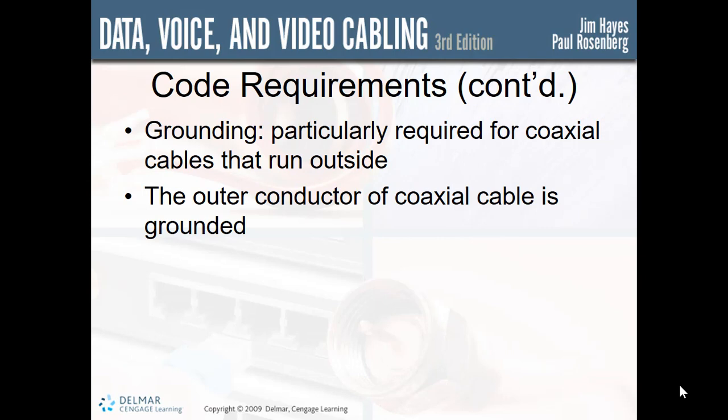Grounding is mentioned in both Parts B and C. Grounding is strictly required for coax cable runs outside of buildings. Although the NEC does not specifically state that all outdoor cables must be grounded, almost all outdoor runs must be grounded to meet requirements of the article. The concern with outdoor cable runs is that they will be exposed to lightning strikes, and in addition to direct strikes, outdoor runs of conductors can have substantial voltages induced into the conductors from nearby lightning strikes.